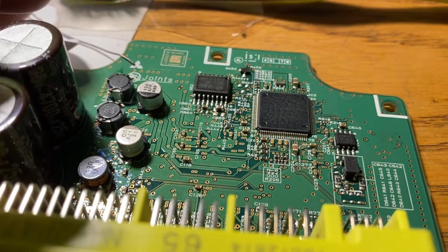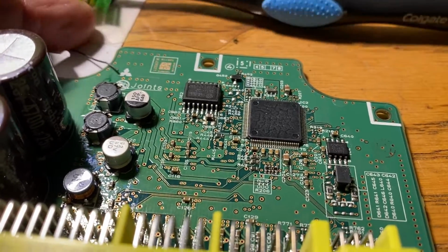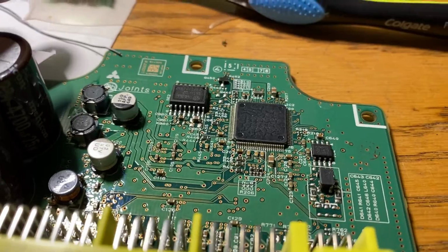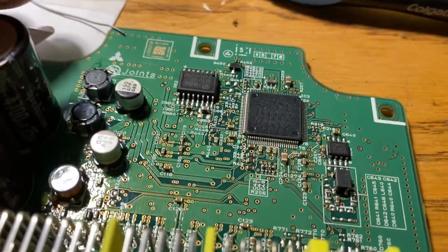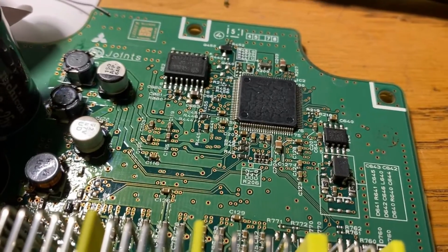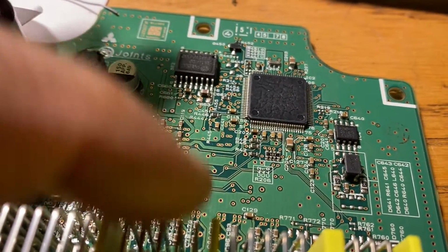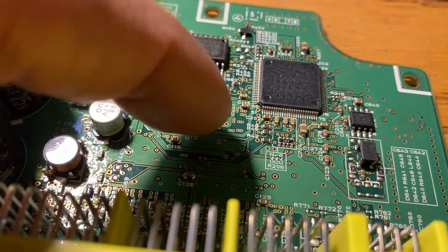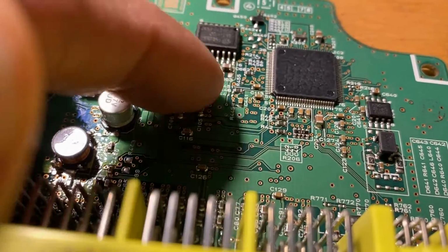And when you try to scan it with a scanner, it's gonna show you internal failure or SRS malfunction. So just to avoid an issue and do the job one time, you don't have to do it many times. Anything with the crystal in circuit, you have to short it out in order to write and read while in circuit, especially write, or you have to take the chip out.